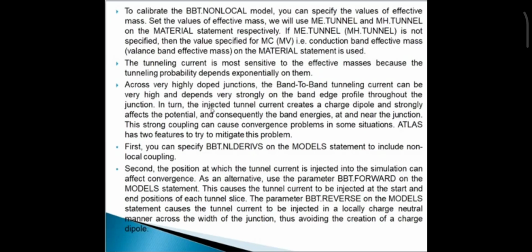The parameter BBT.REVERSE on the model statement causes the tunneling current to be injected in a locally charge-neutral manner across the width of the junction, thus avoiding the creation of a charged dipole.